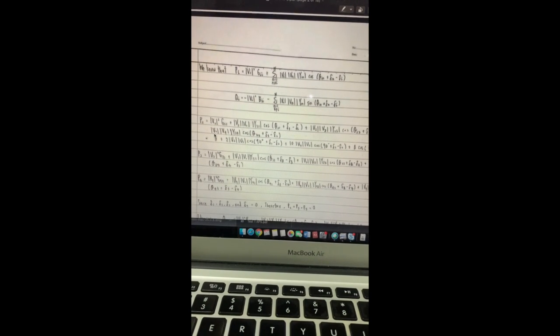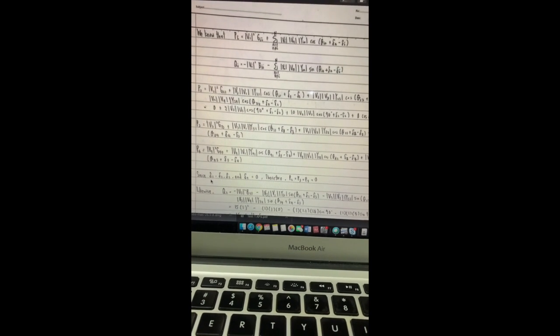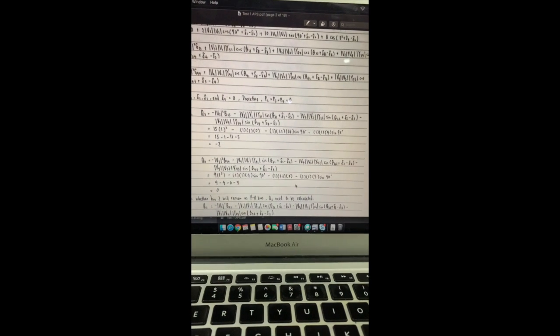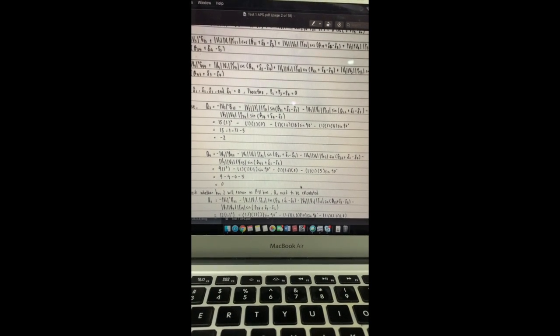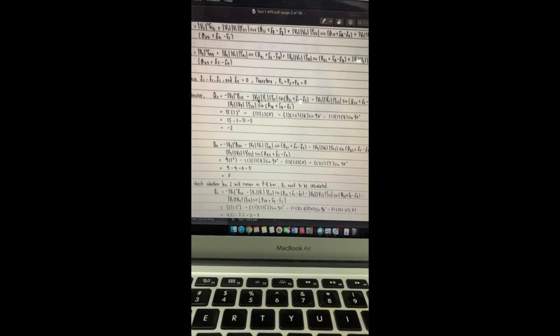Then we know the Pi and Qi formula, so we start to find all the values for P2, P3 and P4. However, since delta 1, 2, 3 and 4 are 0, the P2, P3, P4 for the first iteration are 0. Then the Q3 here we also find accordingly to the formula.